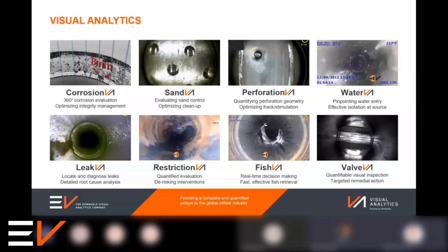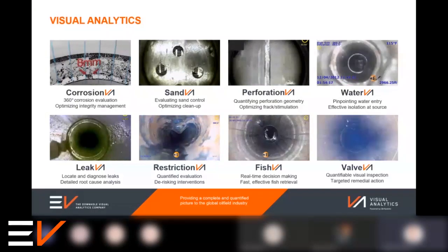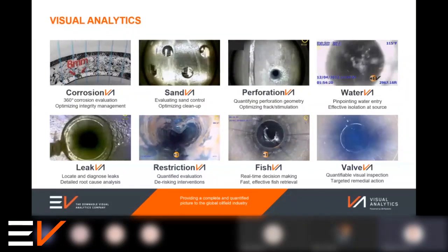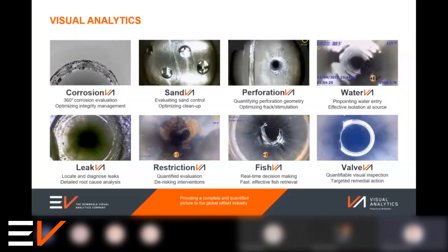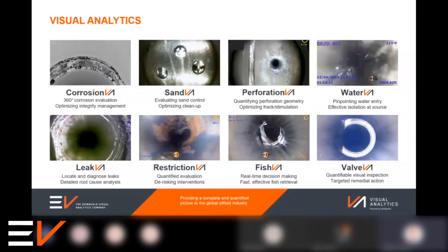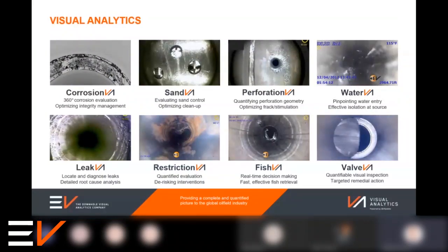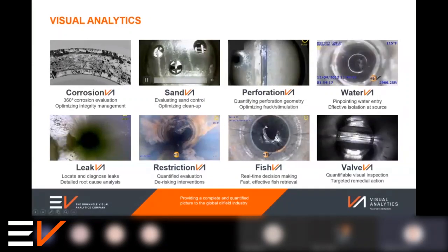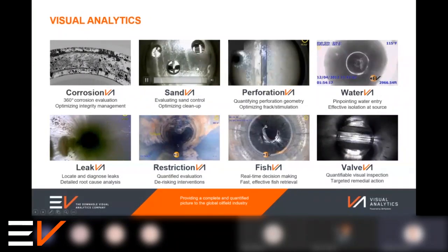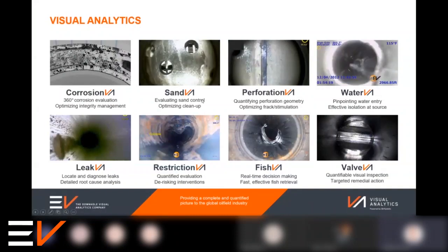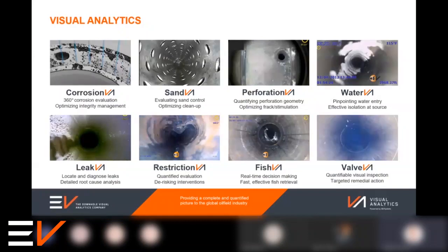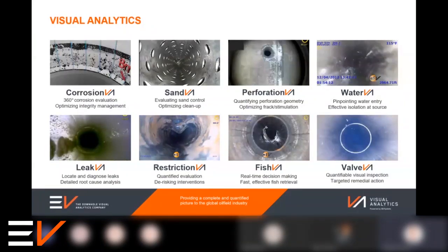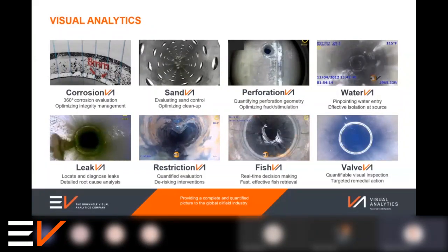Yeah, it's a great point, and it really depends on the screen construction, and this is something that I've looked at with multiple logging techniques, whether it's electromagnetic, ultrasound scanning, or more latterly with video. But this clip we've got here on the video wall is quite useful in that respect, because not only can you see the base hole in these conditions, but in a lot of cases you can also see the filter medium behind it.